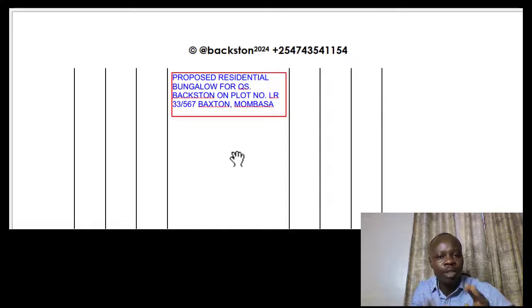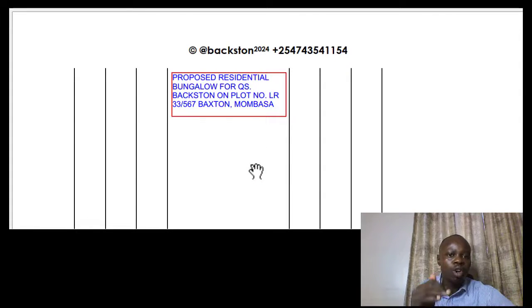Always, if it's not at the title page, of course, we'll also see when we come to build bills of quantities on the Excel sheet, you always provide a page for the title page where you indicate the name of the project and the location of the project. Very, very crucial. That said, after you've indicated that, it's also very crucial that you indicate the items that you are going to deal with in the estimation. Just state for the scope of estimation that I'm going to deal with item 1, item 2, item 3, and so on. So that brings us to you identifying what you have.